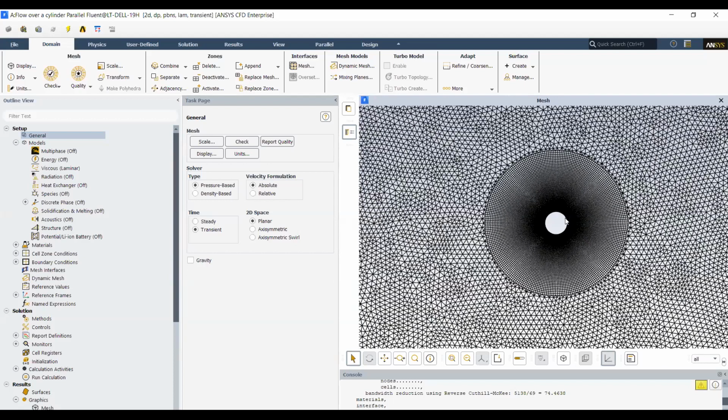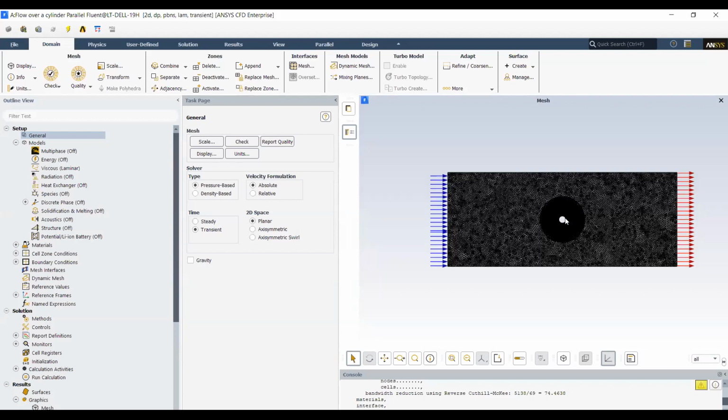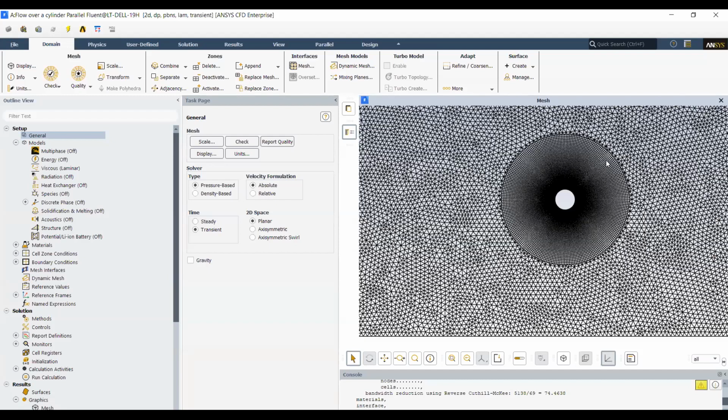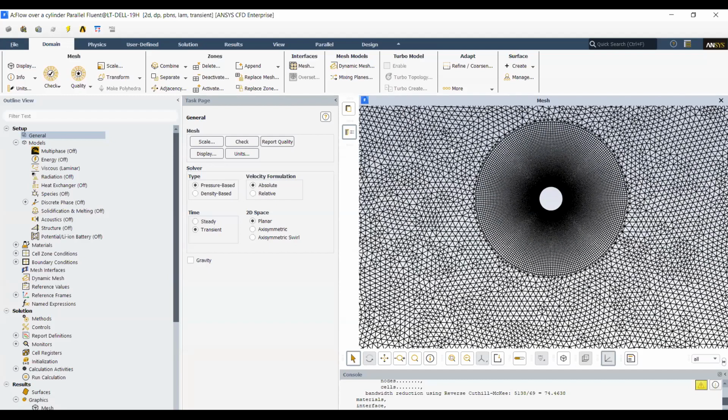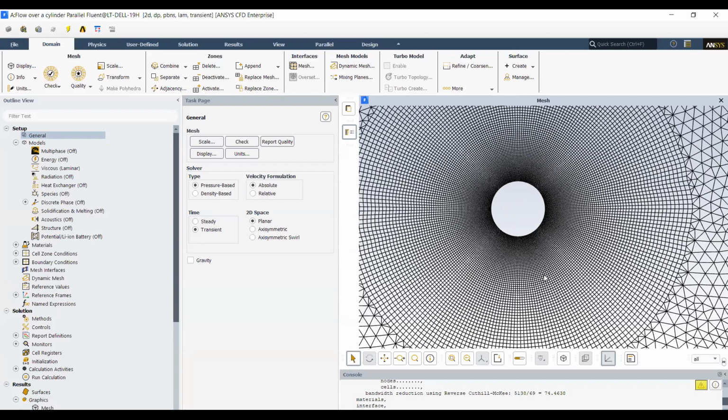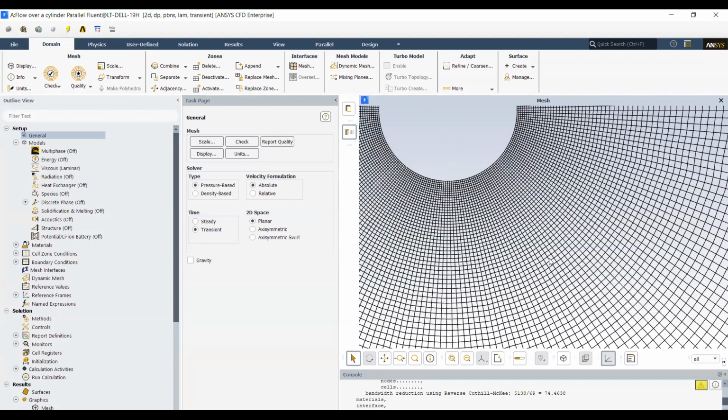Now, this is a standard CFD use case that most CFD engineers do when they're starting off. This might not be important to your application, but hopefully when I go over the settings, you'll understand the steps that you would have to complete to set something similar up for your particular application. Now notice the mesh is not consistent everywhere. In the areas that are closer to the cylinder, I've chosen a hexahedral mesh. A hexahedral mesh, as in you can see a rectangular grid over here.